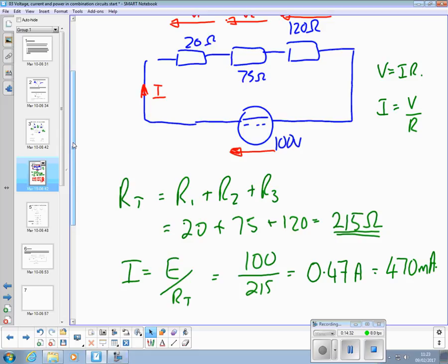That's what's happened. Every time you put a resistance in a circuit, you're reducing the pressure. The voltage is the pressure that forces the current through. So when current flows through a resistance, we always get a potential difference or volt drop across that component. Going around a series circuit, we drop the voltage in proportion to the ratios of the resistors. Bigger resistor gets the bigger volt drop. Current is the same.